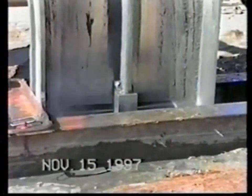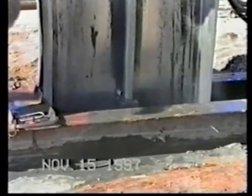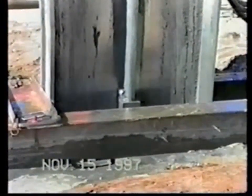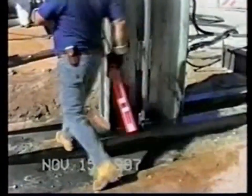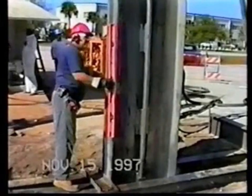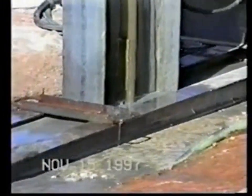Once the beam is into position, it is lowered into the guide box and the water jets are pressurized. The 7-ton vibratory hammer and the high-pressure engines are activated and the penetration begins. Complete cycle times are between 1 and 3 hours for each probe. During the drive, the plumb of the beam is checked several times with a 4-foot carpenter's level. Excess water and cuttings generated from the process are pumped off for analysis and final disposal.